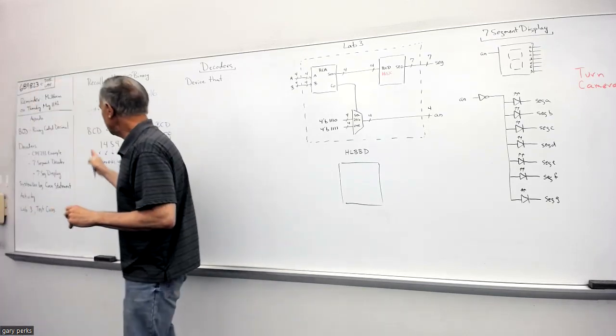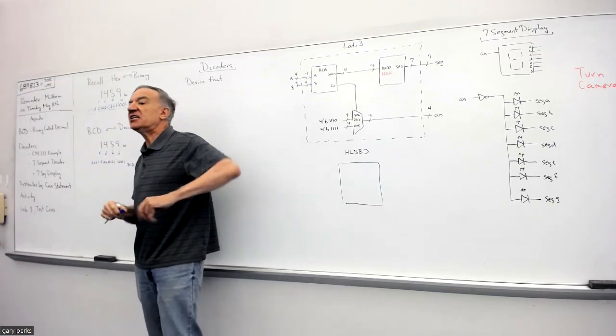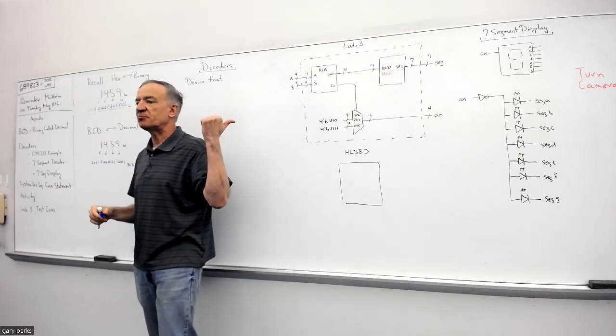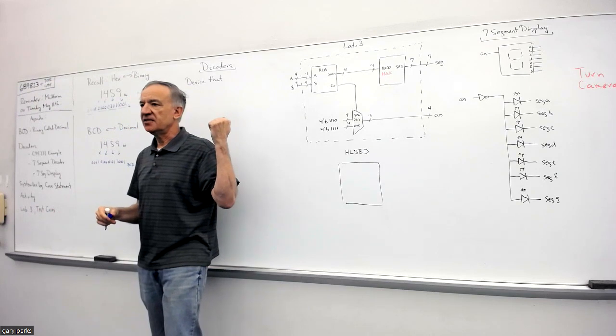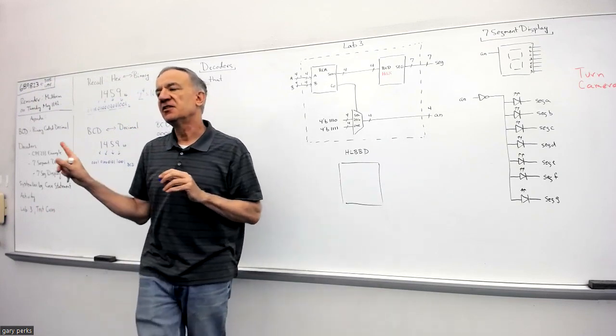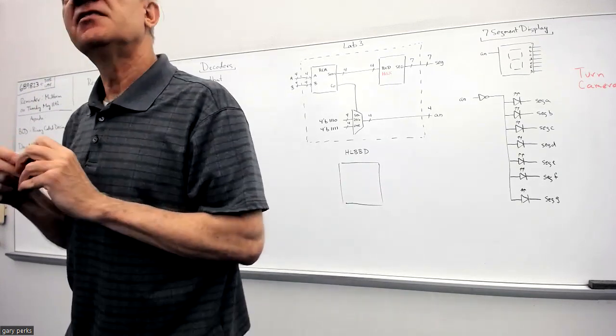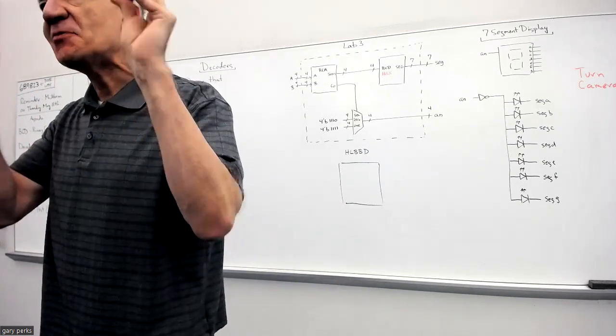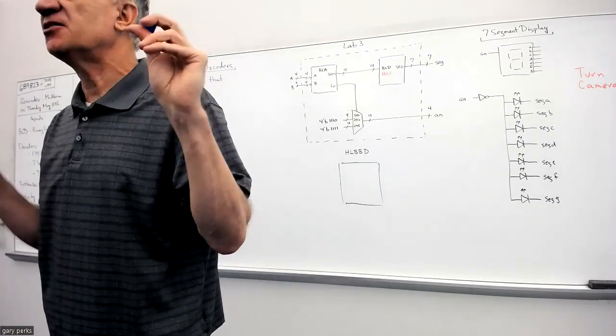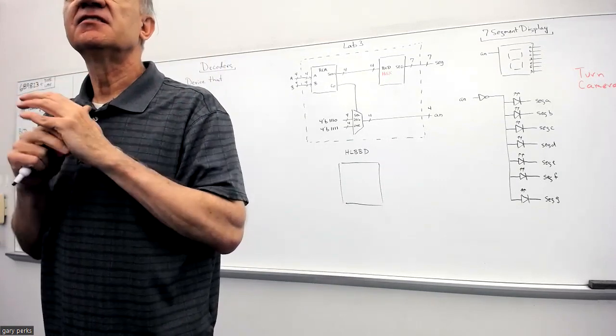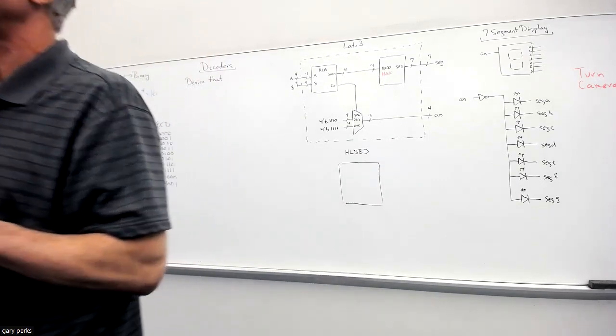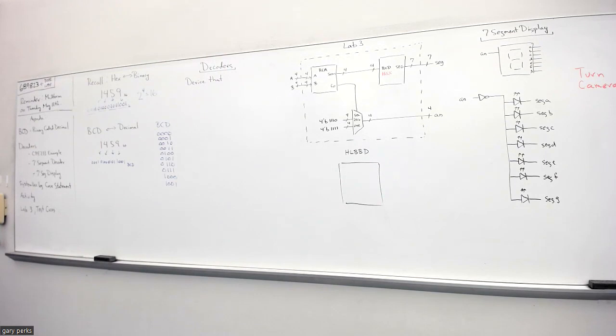The reason for BCD, you'll see coming up, is because of something called a 7-segment display. Okay. Right. So any questions about BCD? The key thing to remember is that we're not doing base conversion. Basically, we're not converting binary.